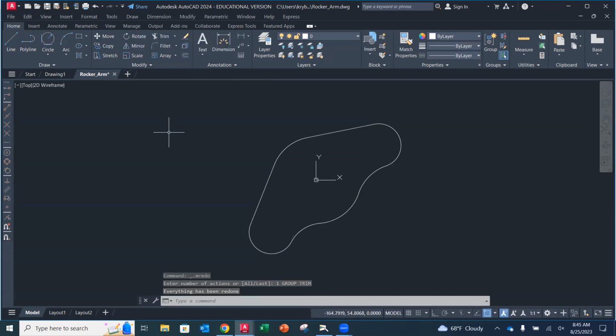So how did trim go for you guys? So with trim, we always want to click on whatever I want to get rid of. And if you hover over it, like if you just kind of go over the top of it without clicking, it'll give you a nice little preview and you'll know if you're on the right part or not. Okay. Questions?